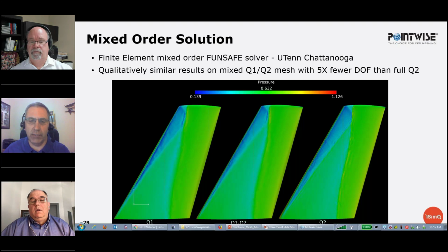And in this case, your mesh is going to be refined and then de-refined as your solution progresses in time, as those features are transported downstream. So really the approach works with either. If you do have unsteadiness, you have to be careful and track that and take appropriate action as to how many of the point clouds you keep around when the mesh is remade conformal to those point clouds.